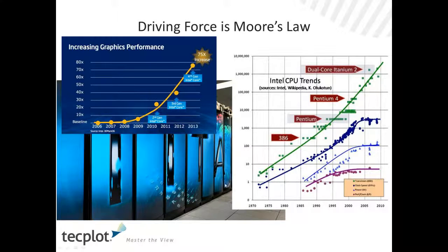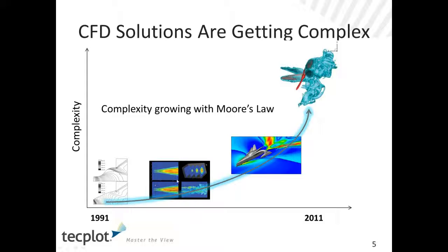So in that context, people have been driving complexity in numerical simulation for years. And in fact, over time, the problems, both size and complexity, have grown with Moore's Law. That's right. One of the issues is that in fluid dynamics especially, but also in other areas of simulation, the length scales involved in the solution are so varied that you really can't have enough grid to resolve them all. That's why there are turbulence models or large eddy simulations, because you're ignoring some of the length scales.